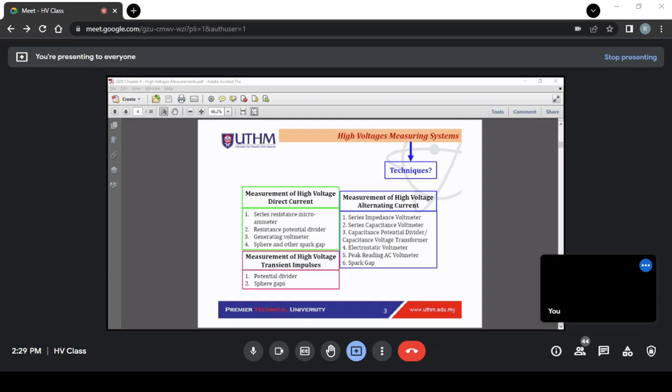Okay, don't worry about the calculation now. It's just a fundamental thing in which the total impedance will be R plus j omega L, divided by 1 minus omega squared LC plus j omega CR. R is resistance, C is capacitance, L is the inductance.